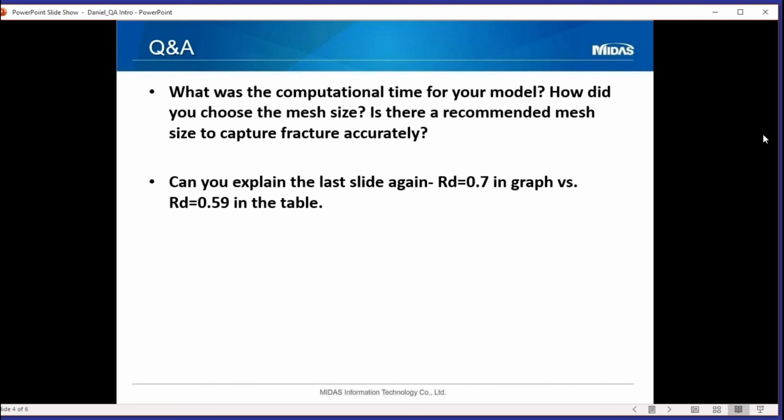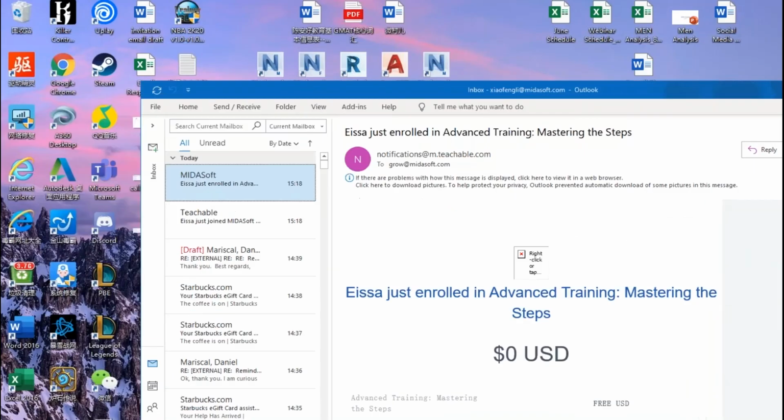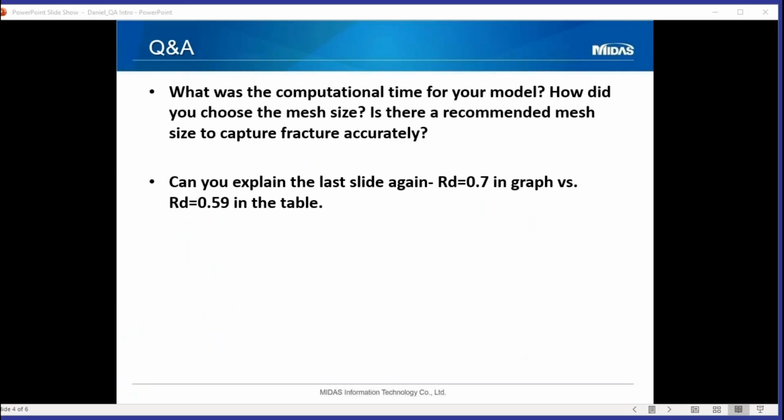In structural analysis, we were taught a little curve that goes up with number of elements, and then it flattens, and it doesn't matter how many elements you add, your results don't change. So sometimes you've got to do a bit of trial and error, and typically I'll try to go small in the elements. That way, I don't have to rerun it again.